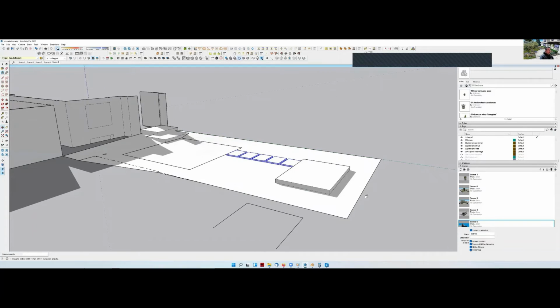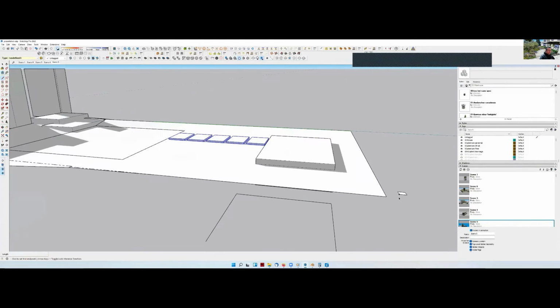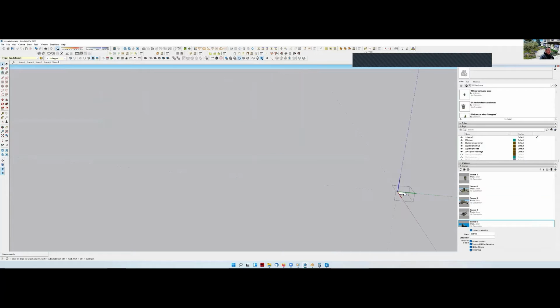And then now we want to quickly create a real to life size pergola over the back patio to create a nice little sitting area. So I'm going to start by creating a 6x6 here, 5.5 inches by 5.5 inches, and I'm going to create that as a component. So again, when you're creating an element to be copied throughout the site, components are the best way to go.